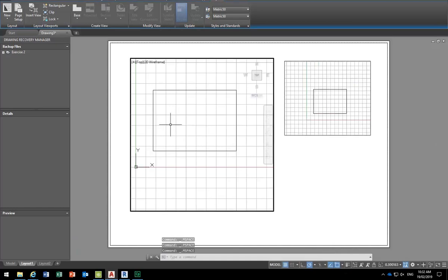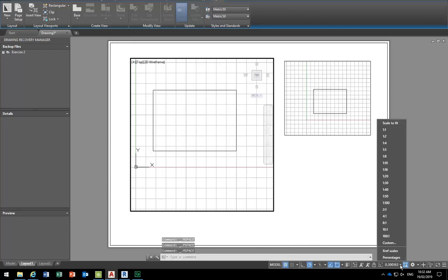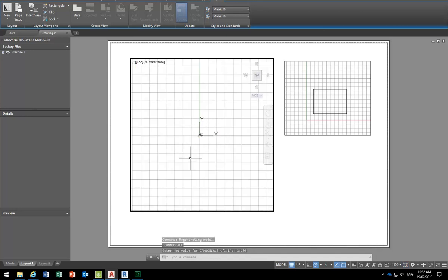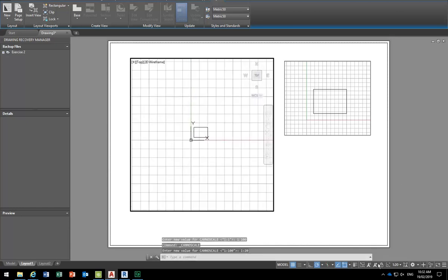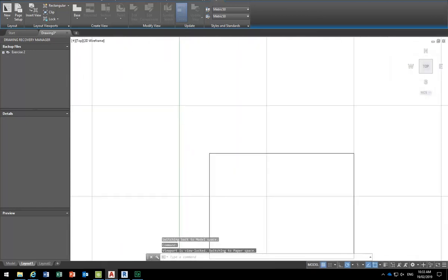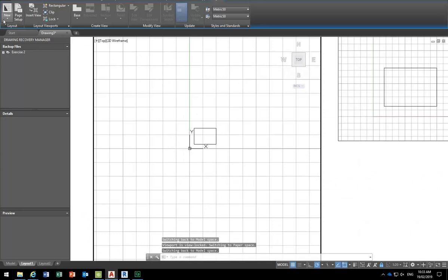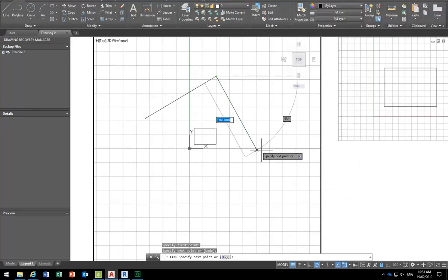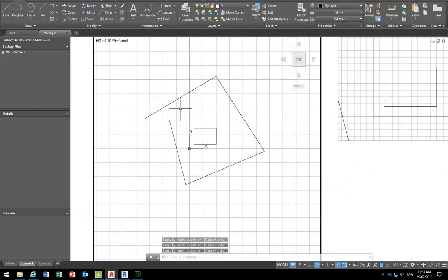And like I said, often I'll be drawing on the page these days because, especially if you've got the scale, so say you want the scale to be 1 to, let's make it 1 to 100, so it's nice and big. And then, also that's a small page, so I can go to 1 to 20 or something. Then you can always lock it. So you've got that lock next to your scale. Yeah, so it's good to think about that, because now, if I zoom, it zooms, I'm still drawing inside that viewport.